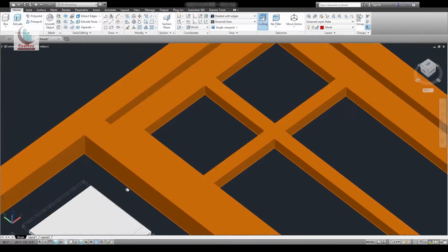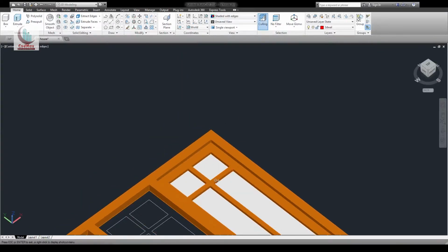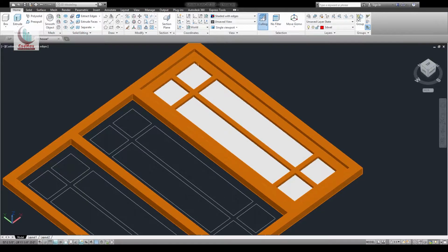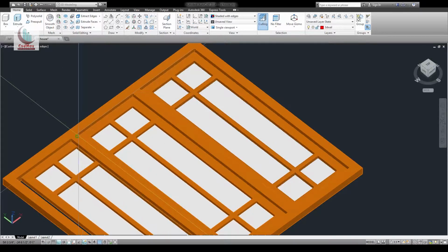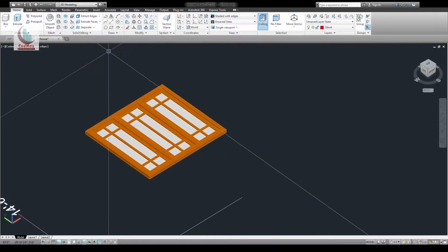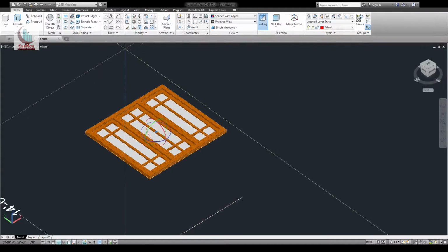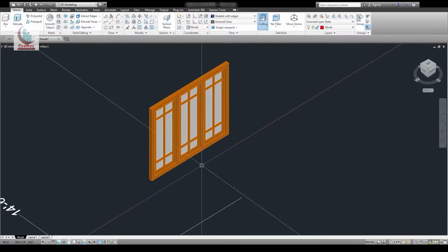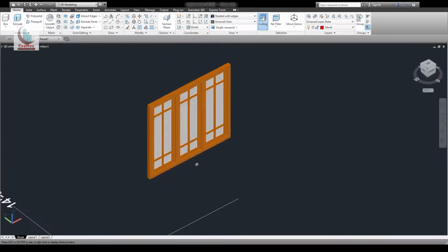Okay, so you can move this base point till here. Now you can copy that, copy previous, it is all the window glass will be selected, and this, enter, base point, second point, and this is the second base point. That is done. Now we can rotate, 3D rotate all this, enter. This is the base point, this is the angle, and you can rotate this. Okay. Good.